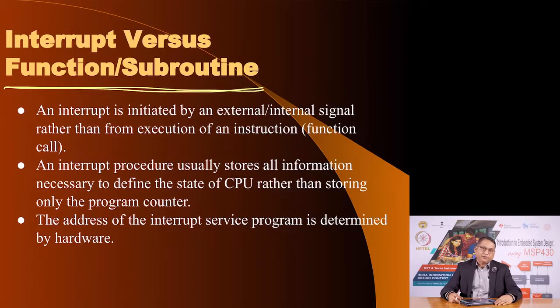In the case of an interrupt subroutine, you do not know when you get called, and therefore you need to store not only the address of the instruction you were executing or would have executed onto the stack, but also the state of the microcontroller. The state of the microcontroller here refers to various flags like zero, carry and so on. So, even those need to be saved on the stack.